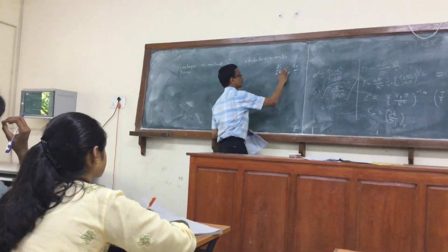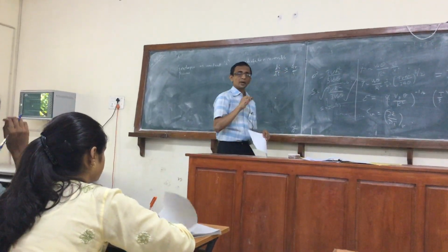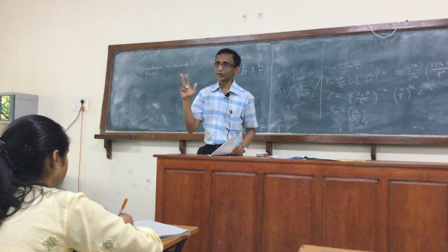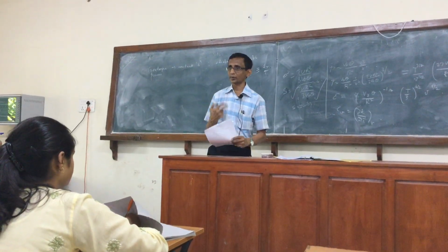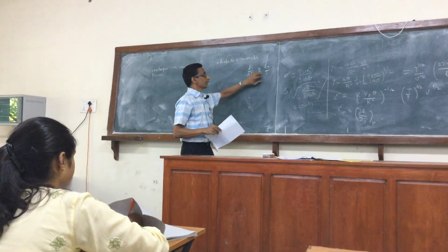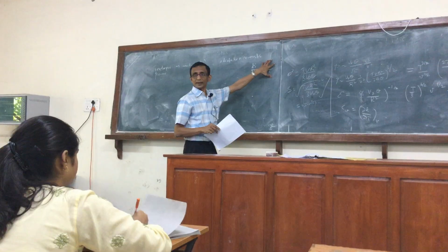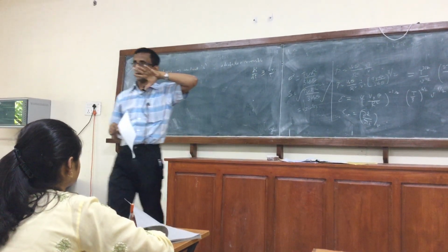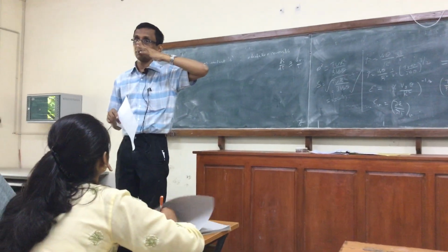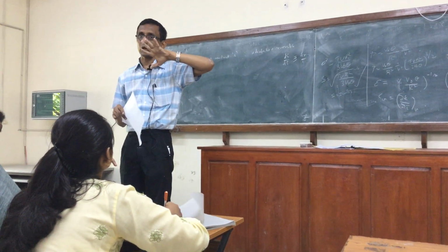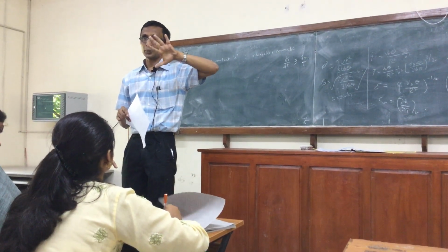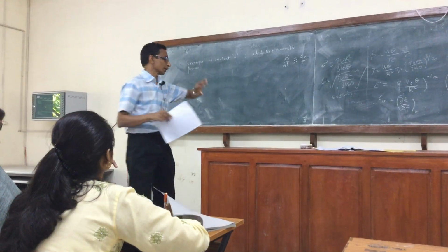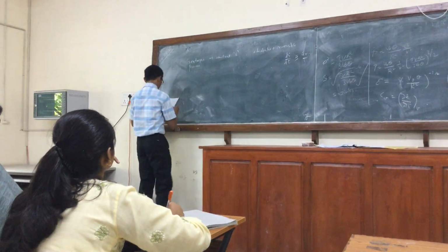However, if it's not a reversible process, then you have the Clausius inequality, provided again the fluid is the same throughout. And so if the process is adiabatic, we can only say that the entropy will increase in the process. It will not necessarily remain the same. So you have to be very careful. Not for all adiabatic processes will the entropy remain the same.